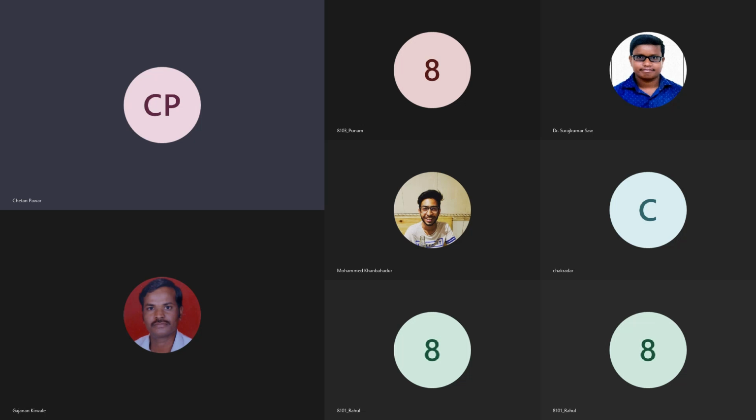You select the VSD 1 volt, okay? And you keep a VGS variable. You keep VGS is equal to VGS. The DC voltage of VGS should be variable, okay? You just need to make those two changes.